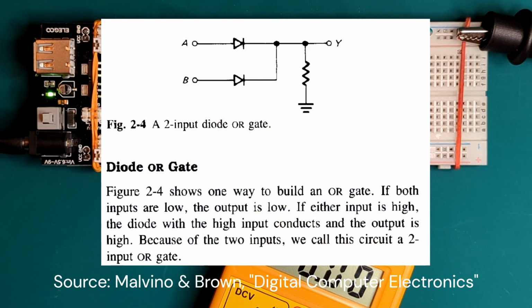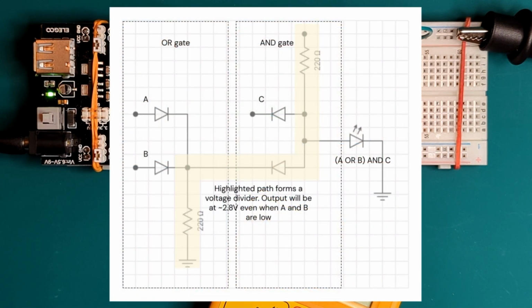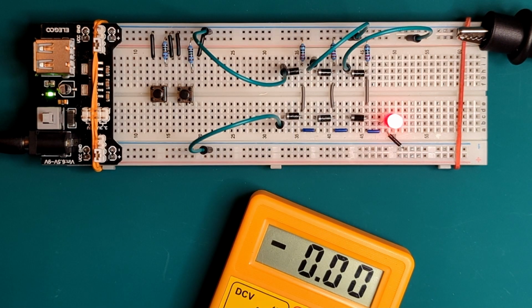You can also use diodes to build OR gates with forward diodes, which will have a similar issue, dropping voltage for the highs rather than increasing the lows. And they are also quite picky on the inputs. If you combine them with other inputs with pull-down resistors, like the diode OR gate with the diode AND gate, you end up with the intermediate voltages that we had when we built the initial button. The final problem is you cannot build NOT gates with diodes.